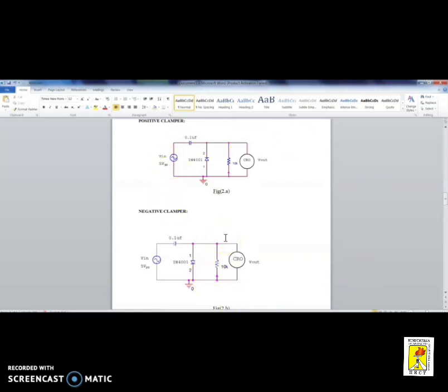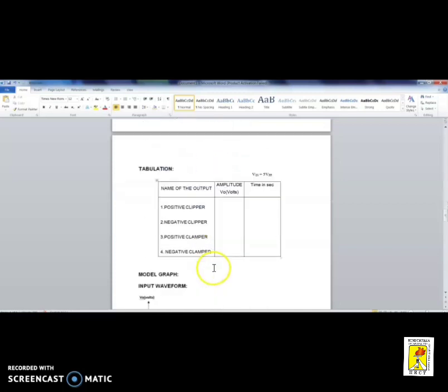We can also design biased clampers, and move the levels as we need accordingly. Generally, clamper circuits are used in television receivers to restore the original DC reference to the video signal, and also to produce a DC voltage whose value is a multiple of the peak AC input voltage. These are a few examples of where clamper circuits are used.